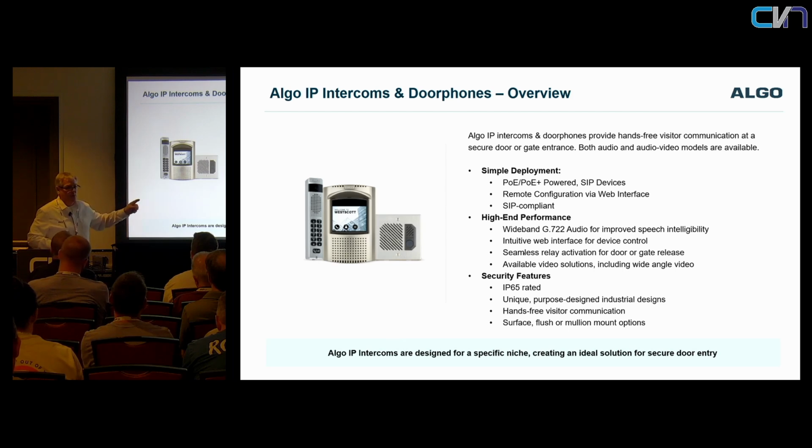We build a 2-piece version of that because you get into a lot of situations where you're migrating people that have legacy infrastructure, like in the Northstar days, Algo actually built a Northstar digital phone. It was actually emulating one of their proprietary phones, and it could be up to 1,000 feet away, where you can't necessarily get a drop there. You could be at a gate, and they'd have an analog device there. So what we've done is we've built a 2-piece version of this, where you'd have your control unit, looks very similar to this, sits in the IDF, registers on the network, connects to Teams, single pair connection up to 1,000 feet away to the door station. Okay, so it's great for retrofits.